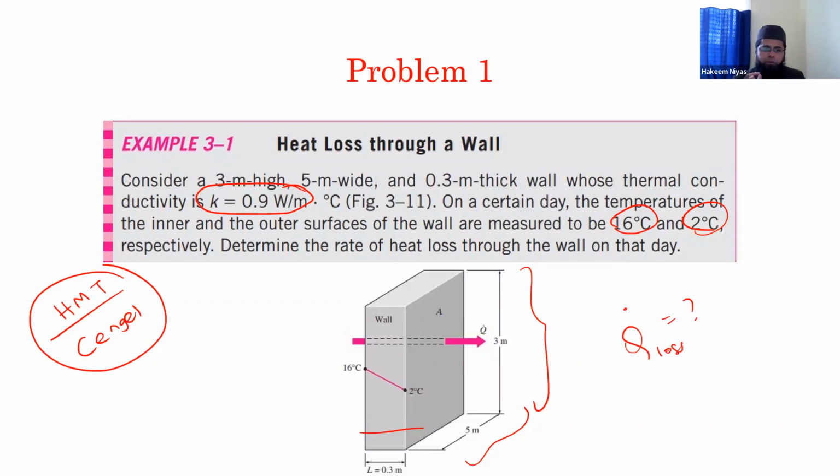One more important point in modeling is we should not build our final stage model initially itself. We should go step by step. We have so many physics being involved, so much complex geometry. We try to model a simple geometry with one physics. We run the model without error, then we add one more physics. We keep on adding physics and we are able to solve without error.